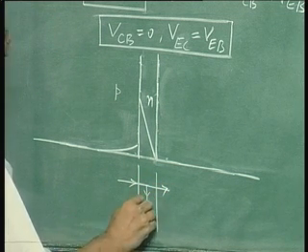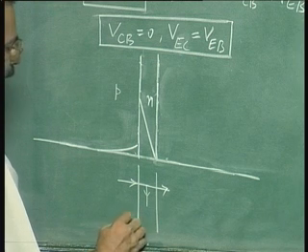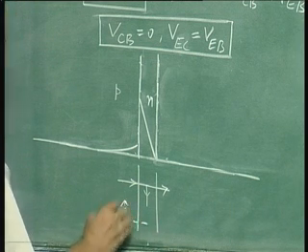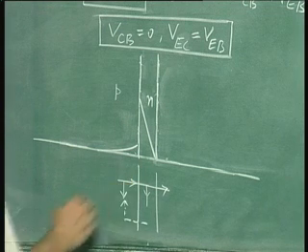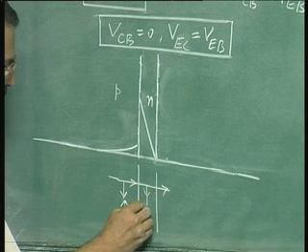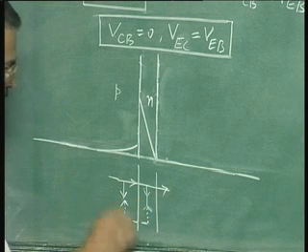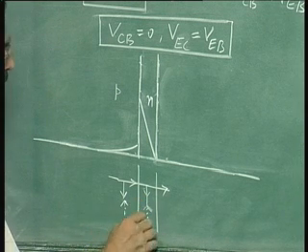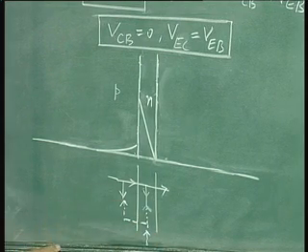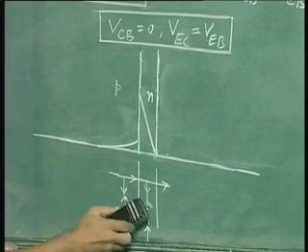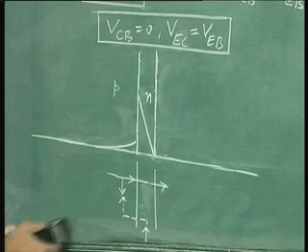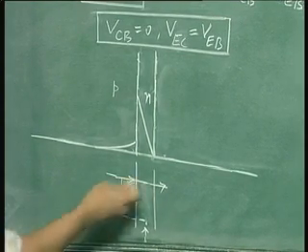You have electron current injected from base to emitter, and this electron current recombine with holes. These holes which are recombining here need electrons for recombination. So this is the electron current, and this electron current is supplied by the base. Again we neglect this recombination in the base, so we remove this. So this is in fact a very simple flow diagram.